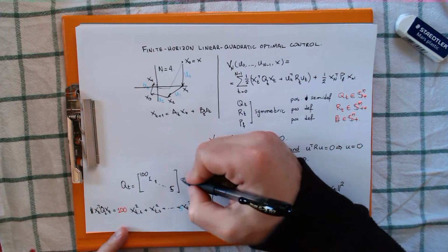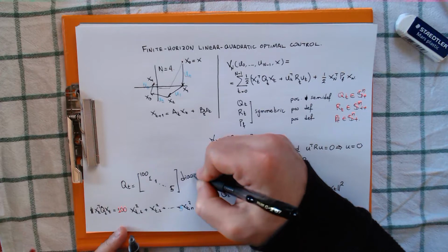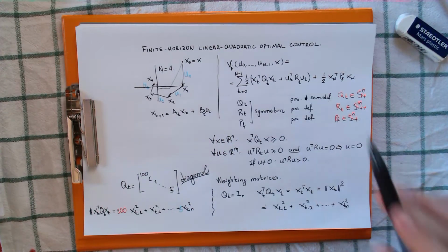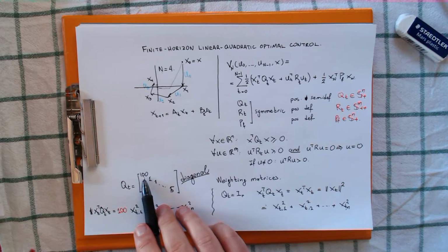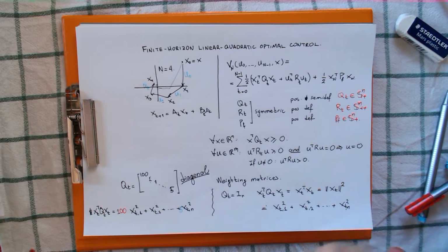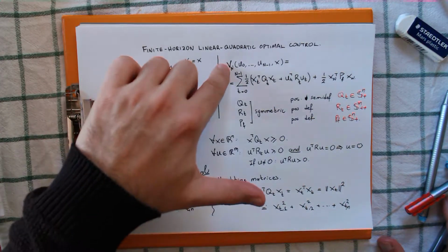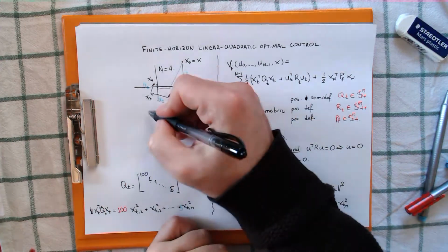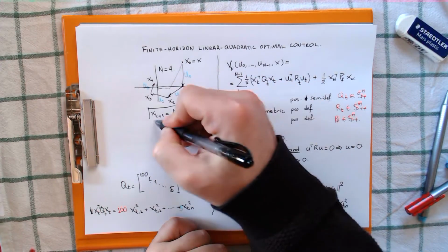So often we do that in practice, we can select Q and R to be diagonal matrices, and the meaning of these diagonal entries is that these are weights for the corresponding elements in a modified norm, a weighted squared norm actually. So the problem now becomes: minimize this function, but take into account that we have a certain system dynamics over here.